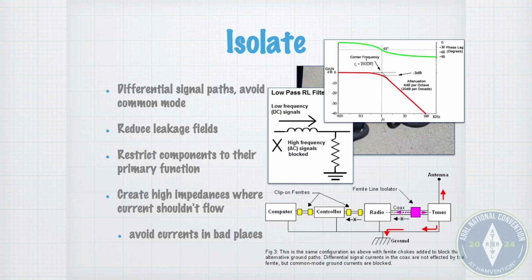And so we put these ferrites on, and the ferrites make the wires into much better inductors than they are on their own. That's like putting an inductor in, and keeps the currents from happening in places you don't want them to be. And you can see that the person who drew this diagram that I kind of stole actually fell for the ground thing, because you can see all these ground connections here that are not necessarily doing what you want, because that may allow some communications between the systems that you don't want to have happen.